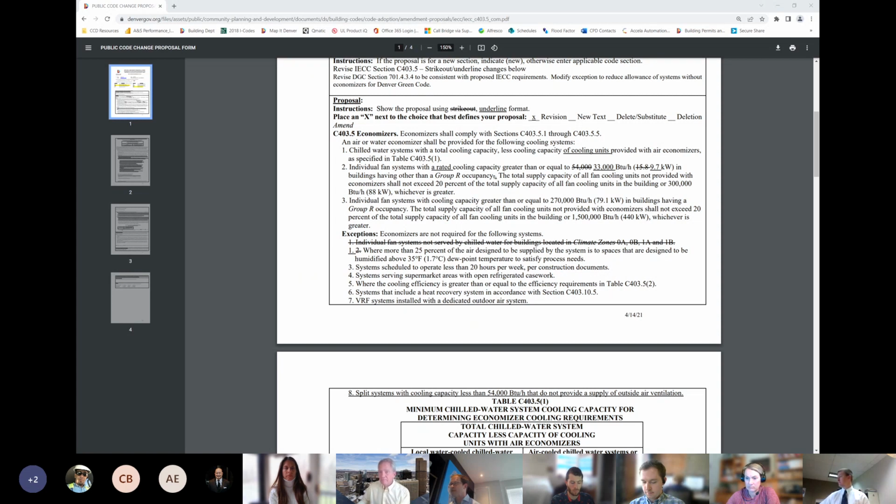Yeah, briefly. I want to give time for other comments. Yeah, that makes sense. I hadn't really thought about the extreme winter condition, and it sounds like the preference then would be to have the VRF systems, if we remove this exception, that they would have to go performance. So provided that there's a reasonable way to model them, then they would likely have to go performance. I'm okay with that. I've seen a VRF system in practice, but I don't have a ton of direct experience with them. But I understand the issues of having the interior-exterior issue. It seems like that would be a similar issue with a VAV system in general, though.